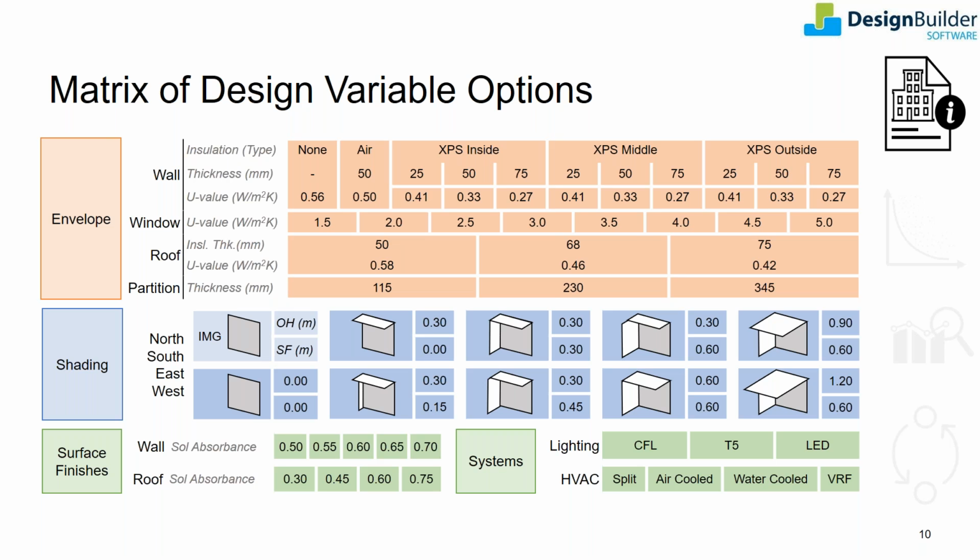The window construction focuses on the U value. Various shading options deal with direct solar gains. Shading has a low-cost way of reducing gains and can be used as a trade-off against more expensive glazing solution.